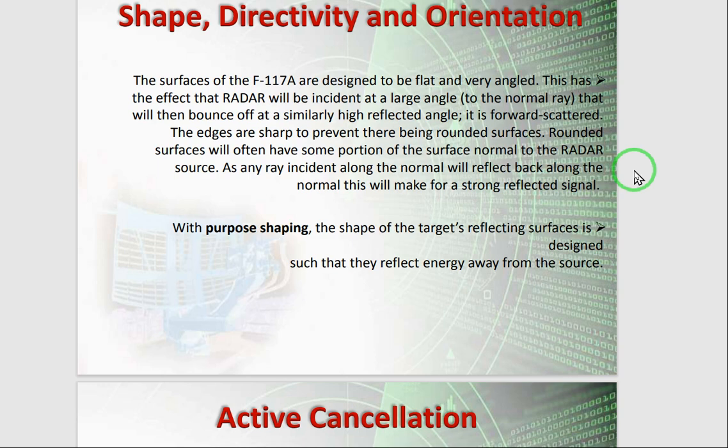Also, in stealth technology, concentration is placed on the edges. Edges should be sharp, not round, because round surfaces will often provide a normal to the surface at which the radar signal can be highly reflective.